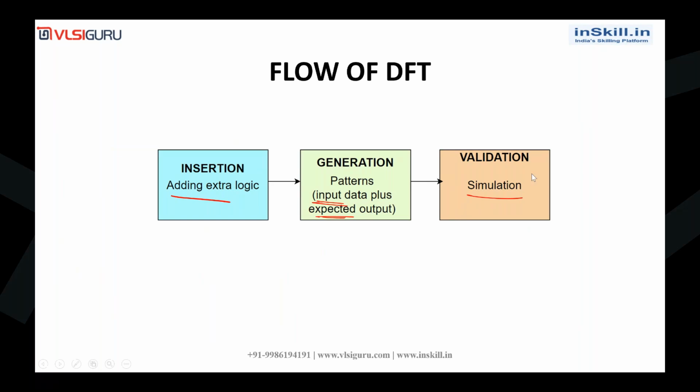Simulation means before delivering the test patterns generated during ATPG to test the chip after manufacturing, we need to validate once whether proper patterns are generated or not. Okay. So before delivering the patterns.